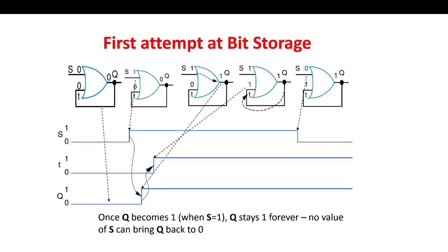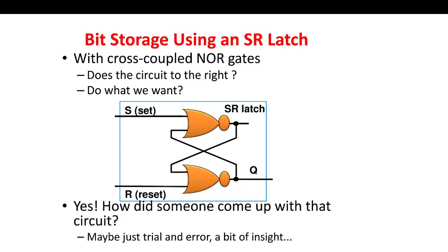So if we consider an example here in the waveform format, it is shown that S and T depend on the output. So if this goes to 1 with the delay, output also goes to 1. Q goes to 1 with this much of delay, and because this is 1, the T is also 1, and it remains at 1 forever, whatever value of the S is applied. So it cannot be used to store a single bit because we cannot now apply a 0.